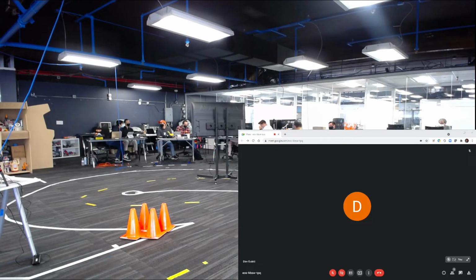The version that the new VESC driver was written on is newer than the one that's publicly available in the repos. Two of the drivers within Autoware.auto rely on the older one. So when you download it into Autoware.auto and try to build, if you use the old one, the old drivers work fine and VESC doesn't. If you use the new one, VESC works fine and the other drivers don't.